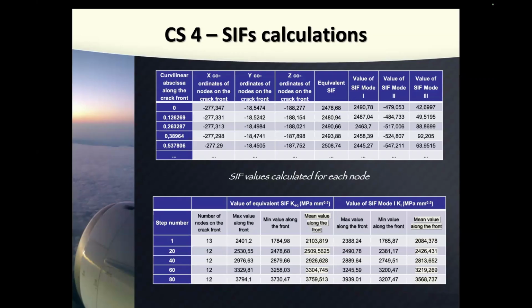Another thing to remember: crack closure. You know, what is that? I mean, the kind of closure I showed you with the intermediate flange, that example with the spar, and one crack stopped. Why did it stop? Because there is a pressure around the front. I mean, all SIF values on the crack front are negative, so the crack will not grow.